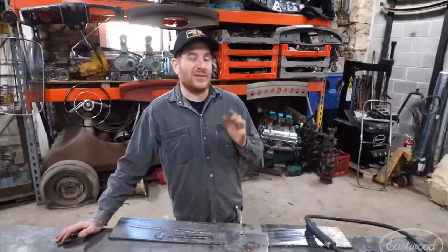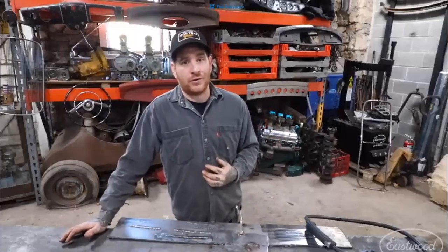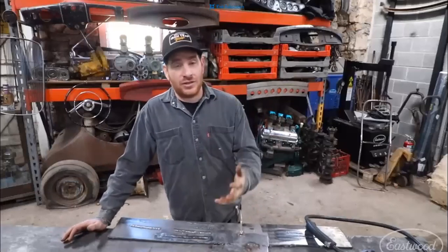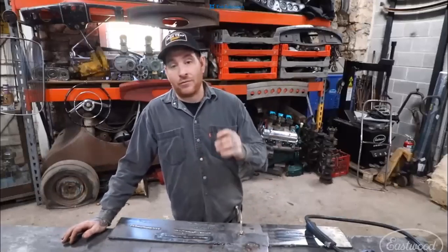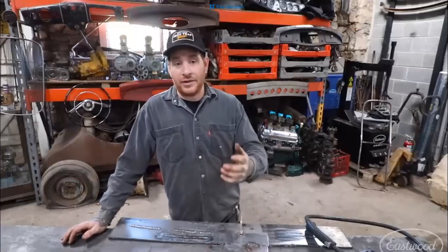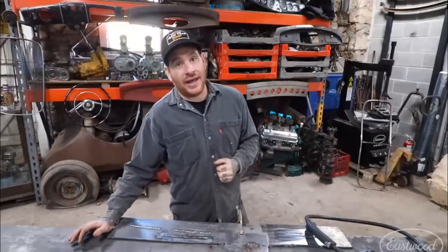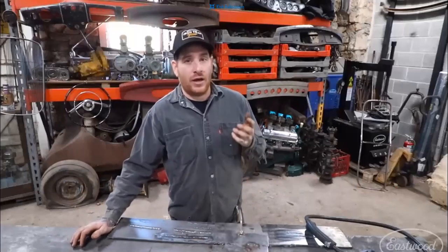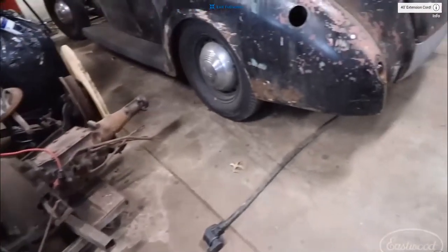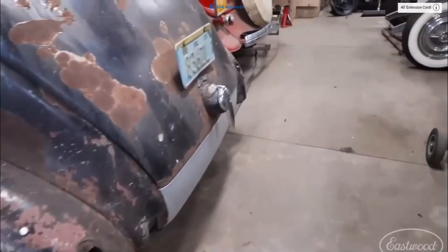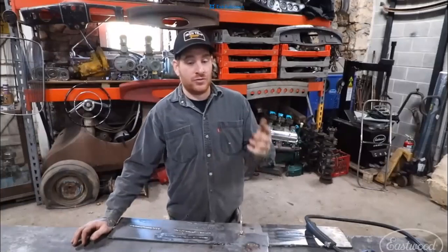The final thing that I see, probably the most common thing when we have calls or I've seen issues with welders as far as the power supply goes, is the extension cord that you're choosing. Not everyone has a shop where you can have a 220 outlet right by where you're welding, and if you're like me, you probably have a bunch of projects and need to move the welder all over your shop. In that case, you need to have an extension cord. Make sure that you're using a heavy-duty welding-rated extension cord. For my MIG 175, I have one of our 220 welding extension cords that has big, beefy wire in it that can handle running all the way across my shop without having any issues with dropping in power.